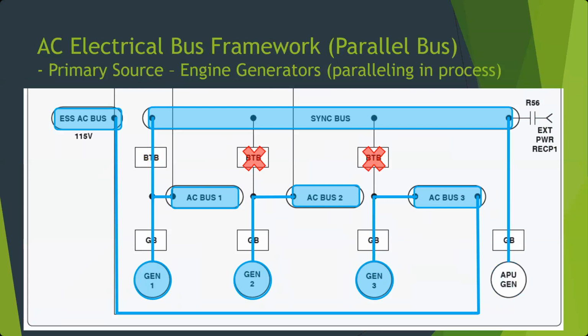And that electromotive force will actually lock those generators together. Even if one's being driven slightly faster or slower than the other, the faster generator will push the slower generator to go faster, or the slower generator will put some drag on the faster generator to go slower, so they stay at the same speed and in sync with one another. But you've got to get them close before you try to hook them up.